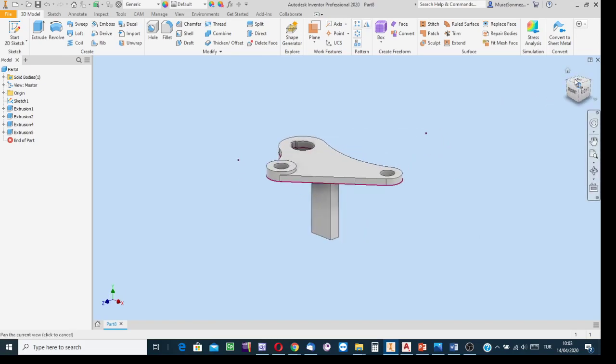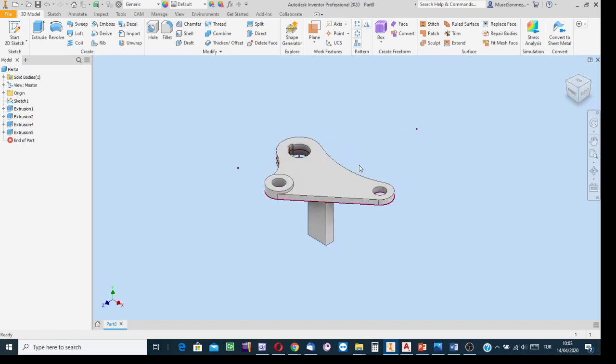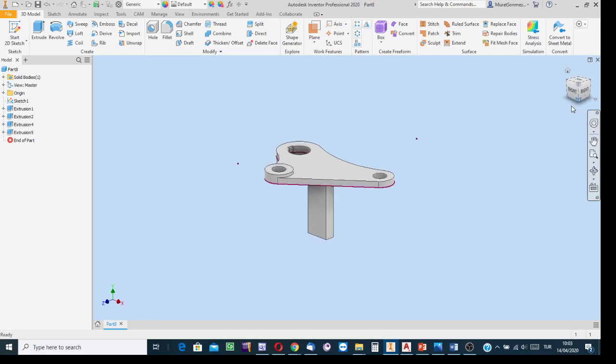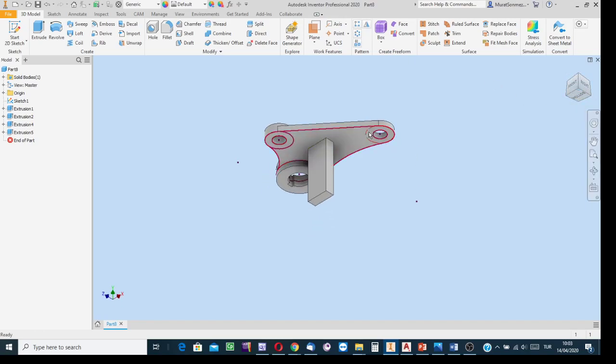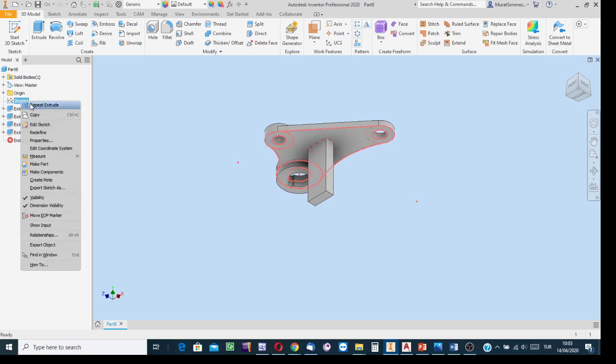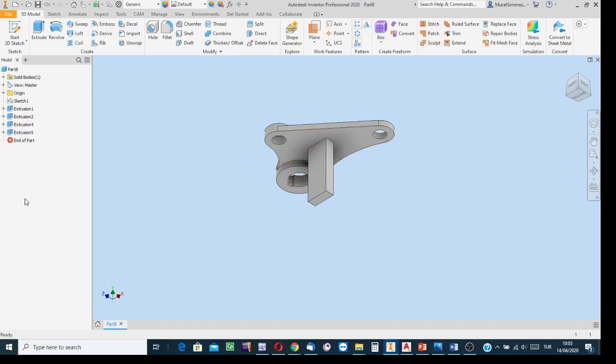And then, this side, I need to have another boss, and at this side one more boss. Okay, restart the process. If the sketch has disappeared, then find the sketch icon at the browser and select the visibility option. If you lost the sketch, since you used it one time, clicking on the OK button in the dialog box, don't worry about it. It is not on the screen, but it is still in the memory.